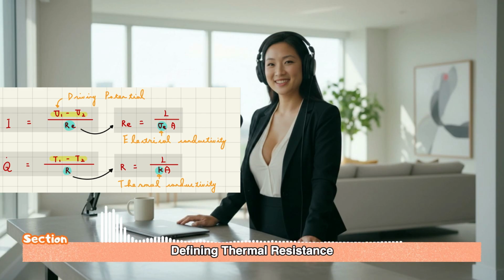Right. In our thermal system, the driving force for heat flow is also a potential difference, which is the temperature difference, delta T, T hot minus T cold. That is the thermal equivalent of voltage. And the flow itself, the electric current I, is a perfect analog for our heat transfer rate, Q dot, which we measure in watts. And naturally, the electrical resistance, Re, is analogous to our thermal resistance, R. So we can write the fundamental equation for steady heat flow as Q dot equals delta T divided by R total. The elegance here is that it lets us look at something really complex, like a skyscraper wall, and just boil it down to a simple circuit diagram with a few resistors.